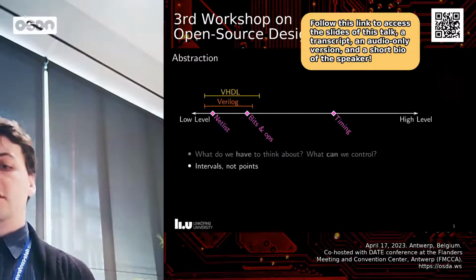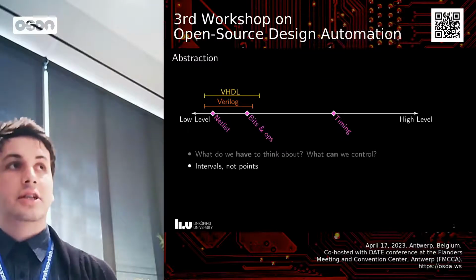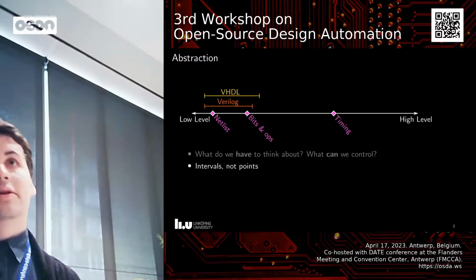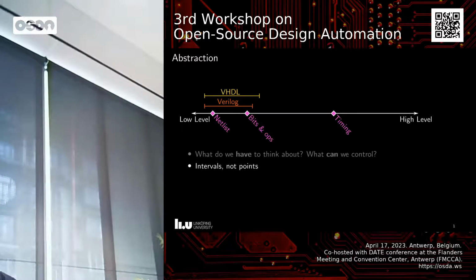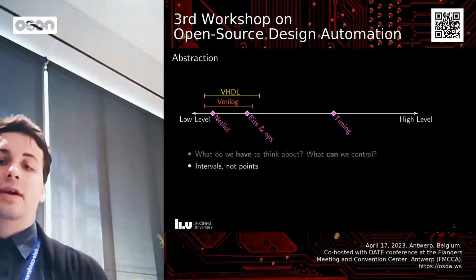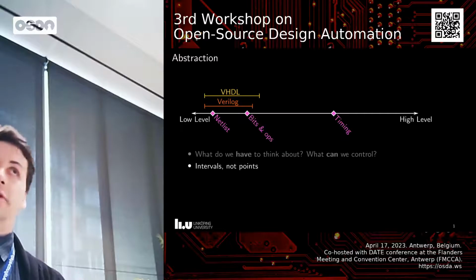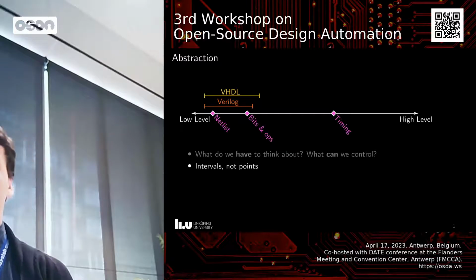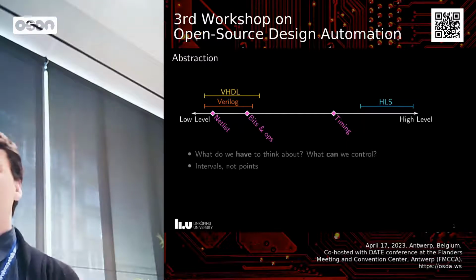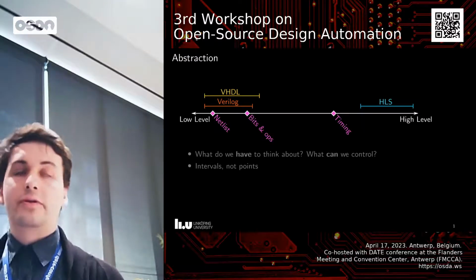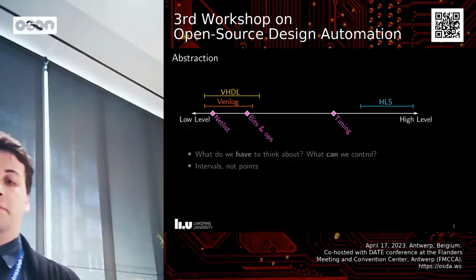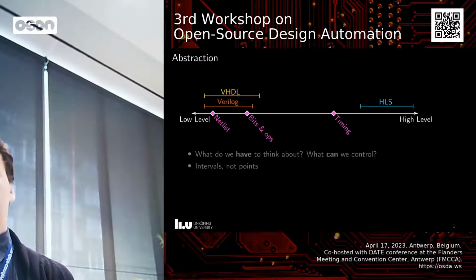So as an example, you have Verilog and VHDL. They are going to be low level in almost any way you look at them, but you can do low level Verilog and sort of instantiate individual AND gates in a netlist, or do high level Verilog, doing more behavioral description and reasoning about sort of individual operations on individual bundles of bits. On the other end of the spectrum, we have high level synthesis. Here we've given up a whole lot of control, but we also have way less things to think about.